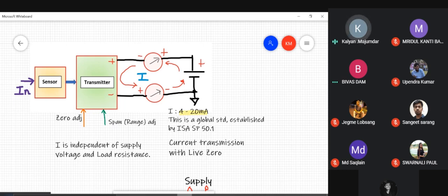So you're measuring the amount of fuel contained at one point where the tank is located, and the information then is conveyed to a remote point where the driver is located, so that you can provide a display, a readout, an indication of the amount of fuel that you have in your tank. So here comes the role of the transmitter. The output of the sensor has to be transferred, has to be conveyed to a different point.